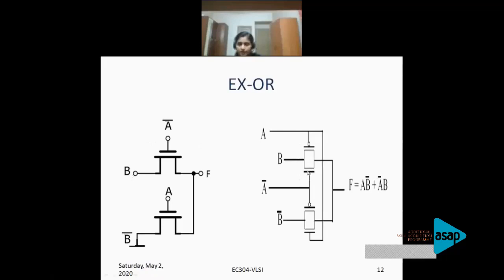So that B dot A bar is here. This was your initial NMOS. Now in order to convert that into a transmission gate, to this NMOS I added a PMOS in parallel. If this is A bar here, then this should be A, so they are complements of each other. So this is A. Similarly, for the second circuit, this is A B bar.